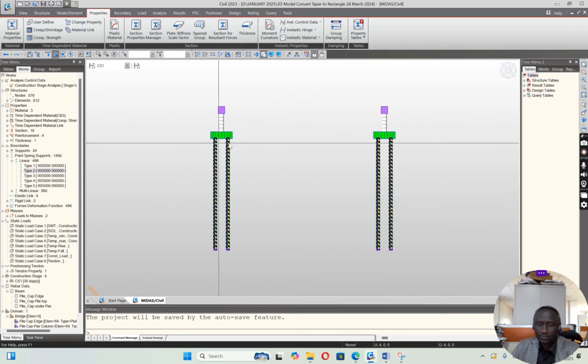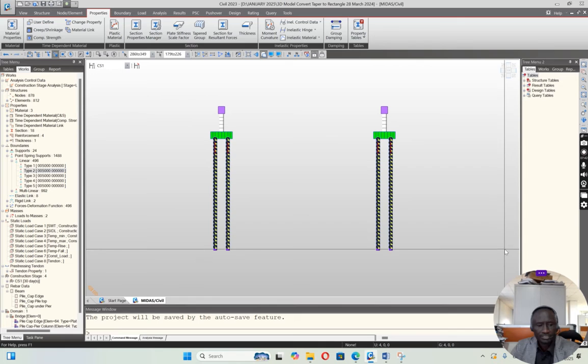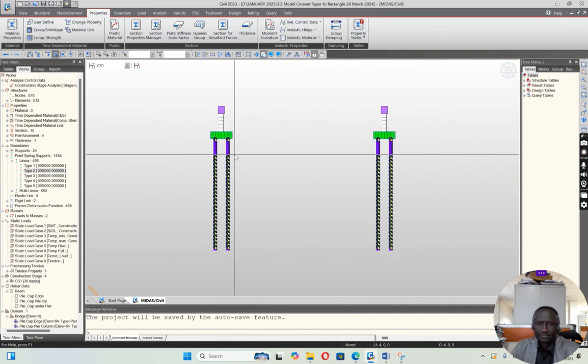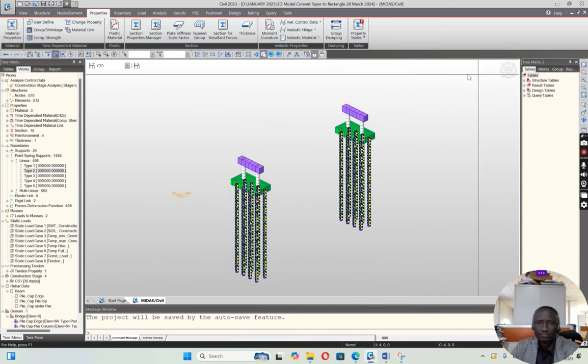So you are able to know the density, whether it is loose, medium, dense, or very dense soil. On the upper part here, normally we consider it to be in water or loose soil. Then, depending on the geotechnical stratification layer identification and definition, you are able to know what is here up to the bottom, so you model properly.